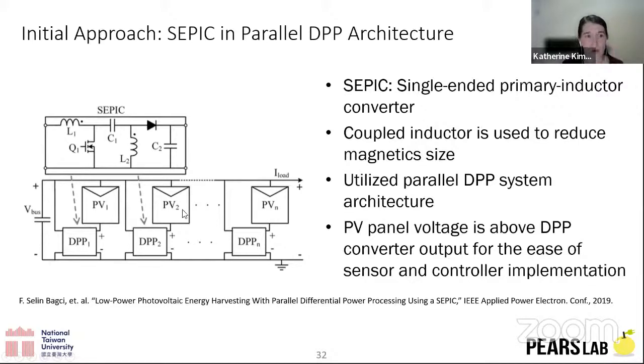Depending on the algorithm, the way we're looking at the algorithms, we're designing specifically to be independent. Most of them would work independently because they're all relative to one point here, so they're all independently controlling each PV. Even if the converter goes down, if it fails in certain ways, it can still operate. The PV can just be a PV with no converter, and it will still provide power. It just won't be optimized.